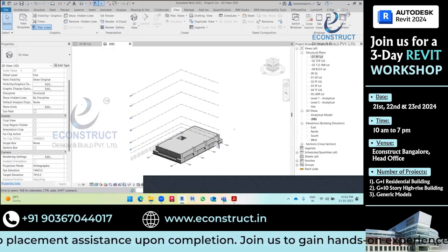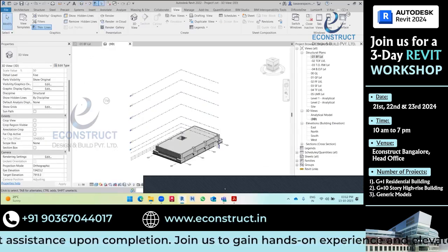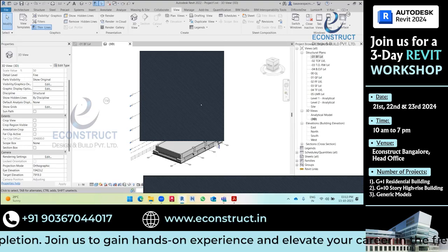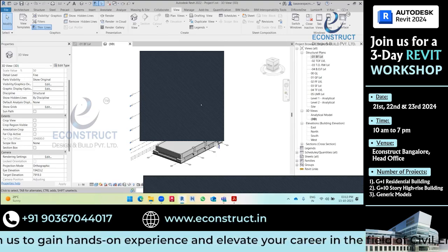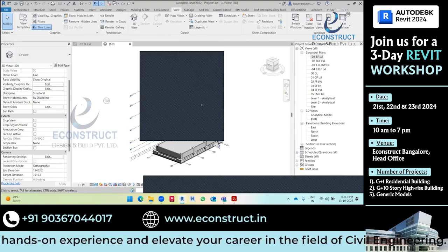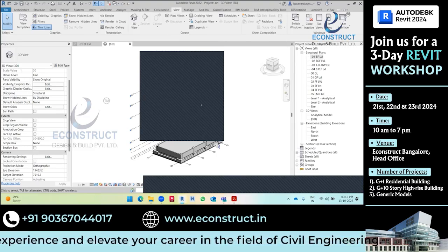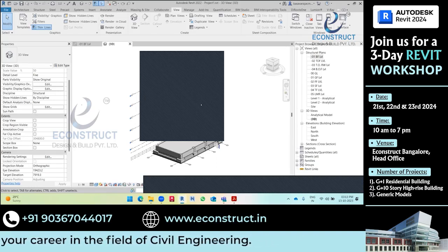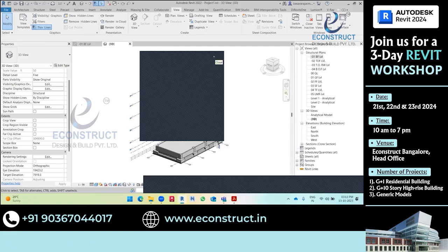And one more question asked in the chat box. What is the standard view range and view depth? Can you please tell me that for structure and for architecture? No, there is no standard, sir. Actually, depending upon your needs, you can set the view range. There is no standard like oh, this much it should be there. Nothing like that. Okay, depending upon your needs, what are all the things you want to see in the view, you can set the view range. That's it. There is no standard like that because always the levels are not same. Level heights depend on the project.